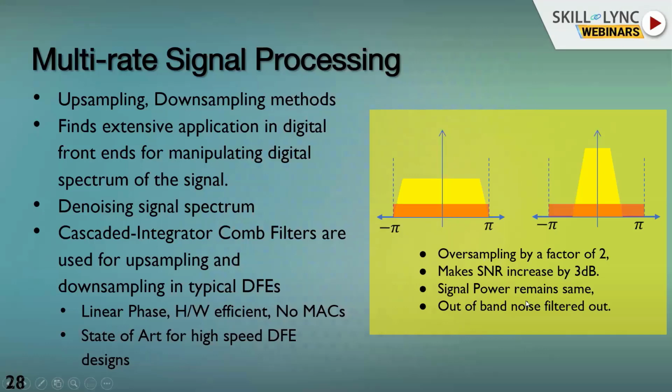in this illustration here. If you are sampling the signal exactly at the Nyquist frequency, which is 2 times the maximum signal frequency, then the whole spectrum is filled with your signal and the quantization or whatever noise the system will have. The SNR, which is the signal to noise ratio of the system, will be the yellow area divided by the red area.